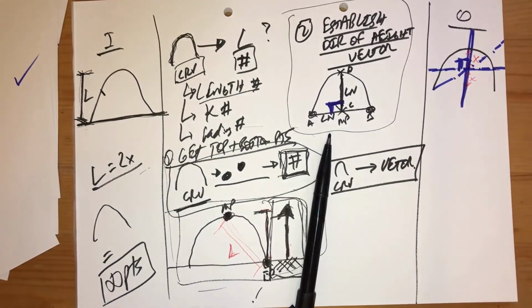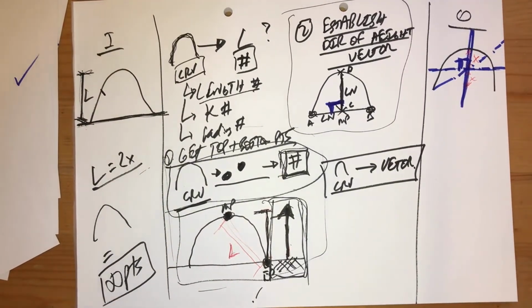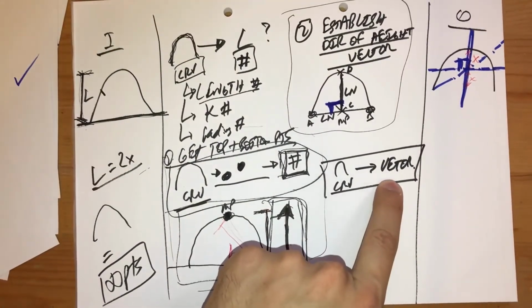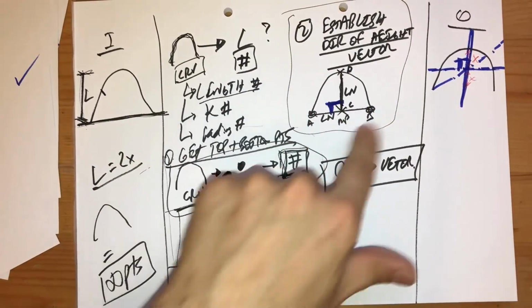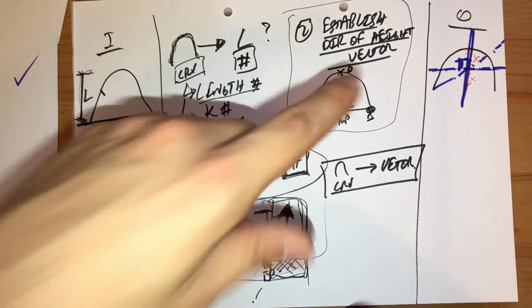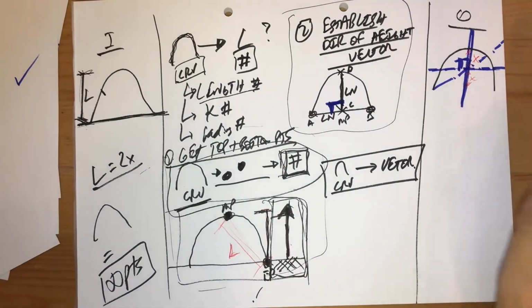Now, with all of that in mind, let's go back to Grasshopper and utilize that knowledge. It's a well-defined problem on paper. We now have the clarity of how we go forward. We convert this curve into a vector, utilizing an algorithm, something like this. And then once we have that, it should be a fairly simple, straightforward process for us to be able to create that axis and mirror about the central plane.